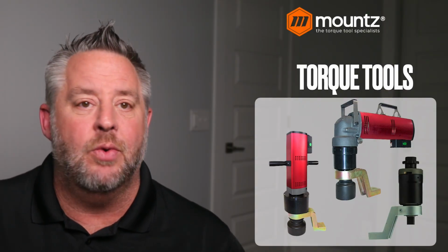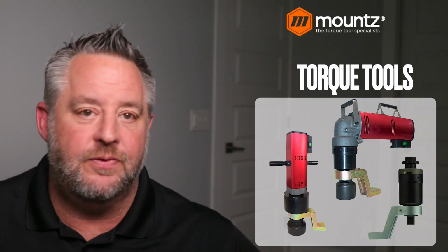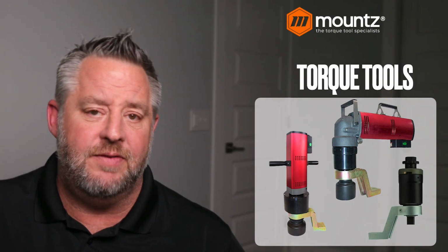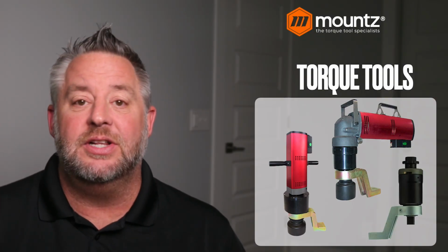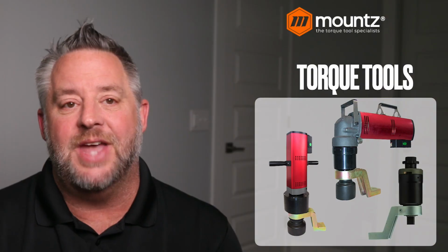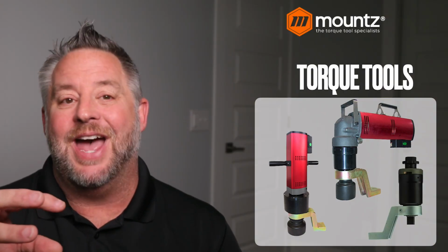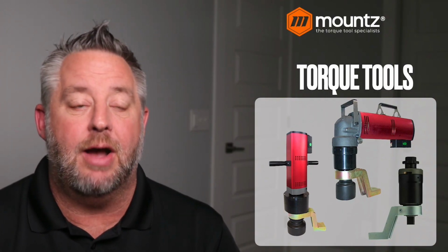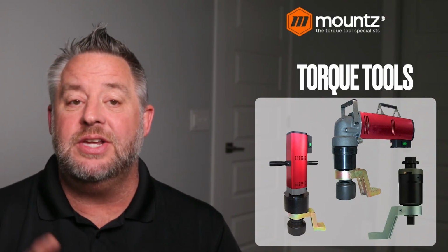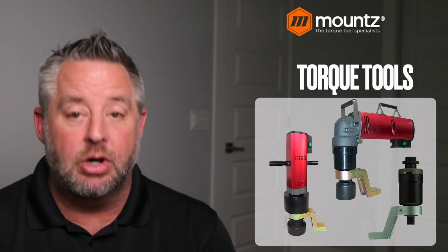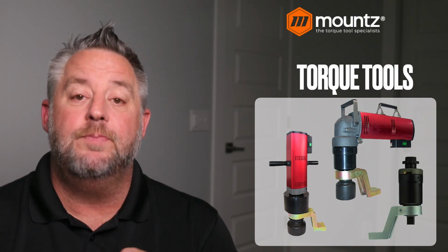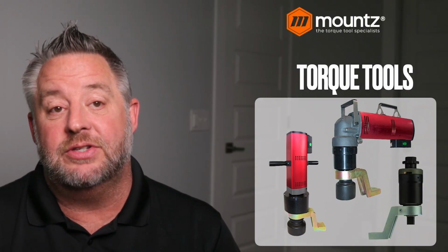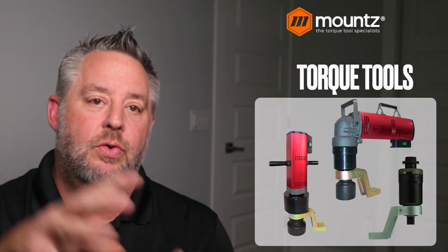We also have very, very high torque types of applications. We may need anywhere from 800 to 50,000 foot-pounds of torque. We can do that through the use of a torque multiplier. That's basically a gearbox that has a certain gear ratio that allows us to put an input in, and it's going to give us a much greater output out. And these can be computer-based controlled to give us a certain precise input and then give us the output needed through that gearbox.